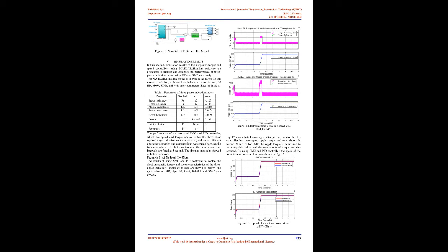An SMC uses a nonlinear control scheme that has the power to control systems to slide along a defined surface to robustly stabilize. It alters the system dynamics to adapt to these behaviors. The block diagram and model of the induction motor using torque and speed controllers are illustrated in Fig 7 and Fig 8, respectively. In these figures, the value of the electromagnetic torque and actual speed generated by the induction motor were designed to be compared to the desired value to generate an error signal, and the error was controlled by